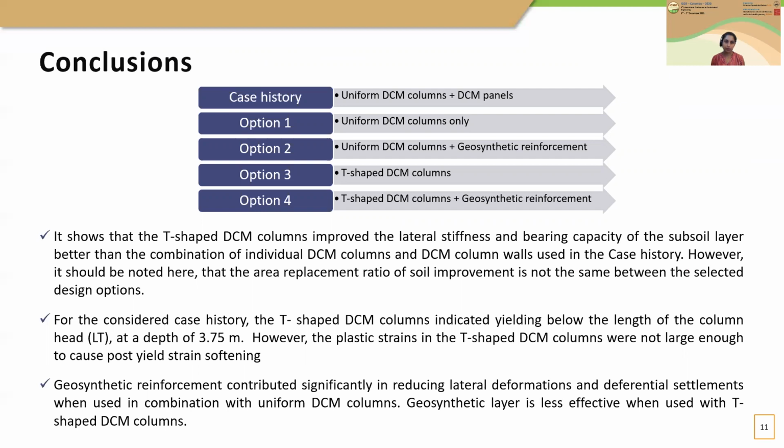Geosynthetic reinforcement contributed significantly in reducing lateral deformations and differential settlements when used in combination with uniform DCM columns. The geosynthetic layer is less effective when used with T-shaped DCM columns.